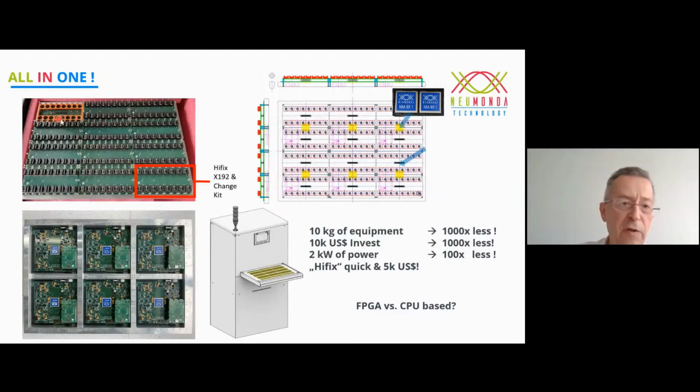Then we have an insulation layer in between, and on top we mount PCBs, for example, with component sockets. You can also put your memory DIMM module slot, so the same way you can test also memory modules. So now the bottom is thermally insulated from the top, and you can put the top in a harsh environment.